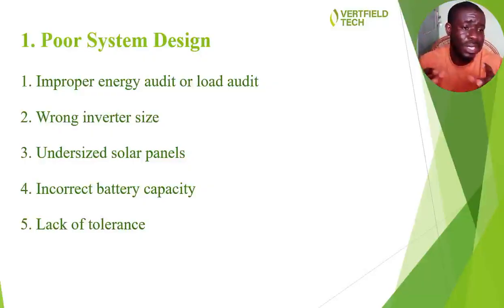Incorrect battery capacity is another thing. When you do a wrong energy audit, you have already failed from the very beginning. Also, when you do not size your batteries properly, you have failed again. Because if the required number of batteries or the capacity of batteries available is not matching up to the quantity of loads that is to be fed, which also sums up to the length of hours you want to run that system, then your battery system will fail.